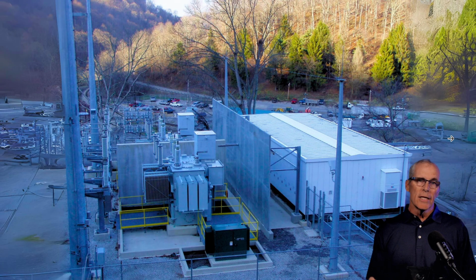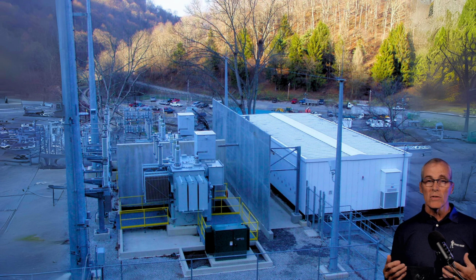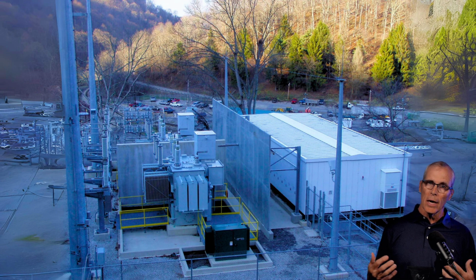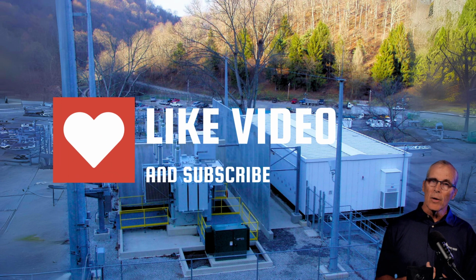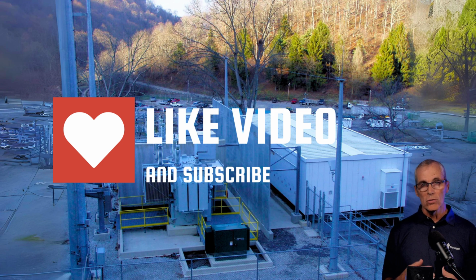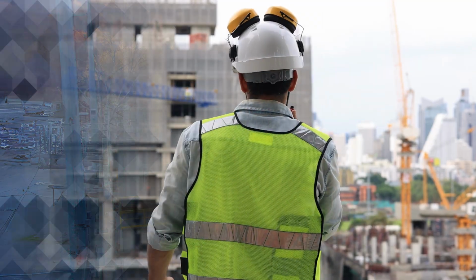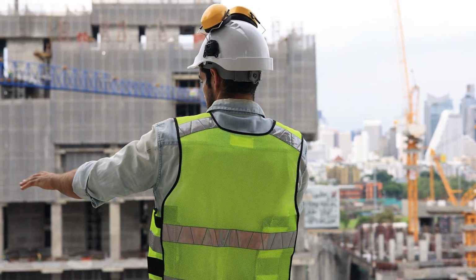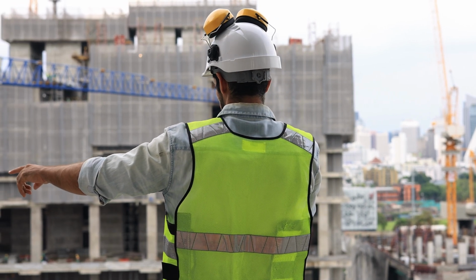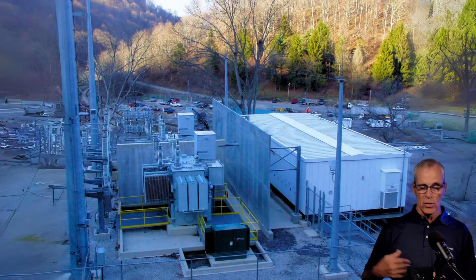So the idea here is that we have situations and scenarios out in our facilities that we want to analyze and figure out what's the right approach for protection. And specifically, I'm going to talk about firewalls today and mostly transformers. But the idea is that when you have the potential for a pool fire, then you want the ability to understand how big of a fire that can be, to know, can it really damage a nearby target?